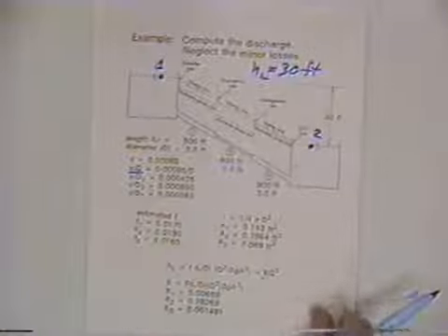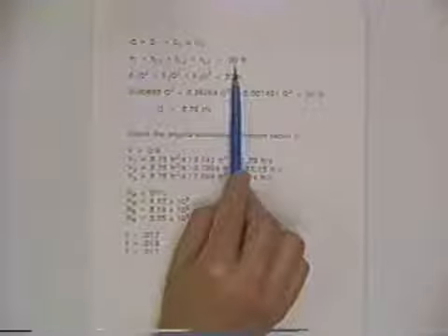To simplify things, we've reduced it down to K times Q squared, as we just talked about. Given the diameters, lengths, and friction factors for the pipes, we can compute the three Ks. And given those numbers for the Ks, we can plug into these basic relationships. We recognize that the total Q we're trying to compute is equal to the Q in each of the three pipes.